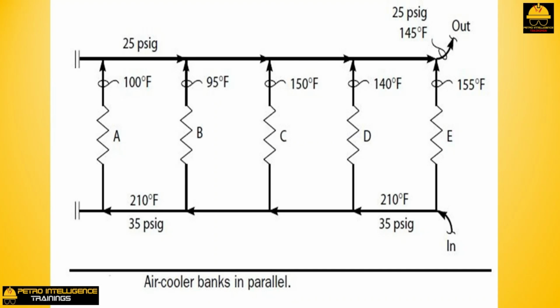The mechanism that causes this often severe flow maldistribution is based on low-temperature dew-point corrosion, as explained below. Here is a rather common example, assuming that the main corrodants are chlorides, in a hydrogen sulfide-rich, condensing hydrocarbon vapor. 1. A small amount of ammonia is injected into the overhead vapor line to control the pH of a downstream water draw. 2. Vapor phase ammonium chloride is formed.